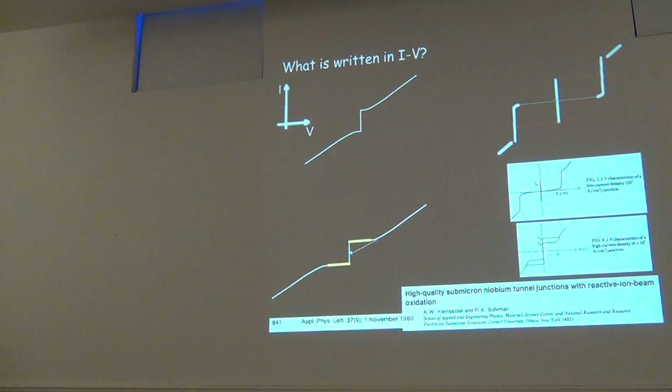And this is not only for the new generation of junctions; you often observe this on hybrid junctions with InAs nanowires, where you see excess current and a lot of strange things, subgap currents. But this has been clear since the 80s.